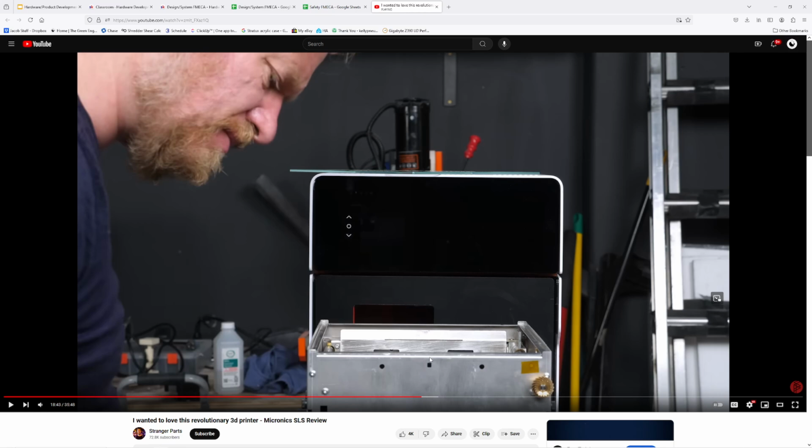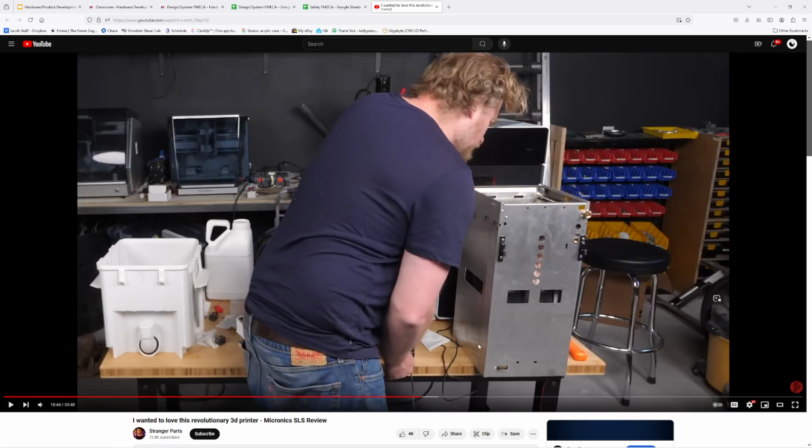So he's talking here, basically, he thinks that this auger is tilted or something, and so it's rubbing against the inside of the tube, and that's why it's jamming up. Or there's so much force on it from the compacted powder that it's putting too much torque on the thrust bearings on the inside, or pinching something, right? I've had some designs like that in the past where I haven't had adequate support when lifting. For example, I built this bike rack for a motorcycle, and when the machine was halfway down, it was fine, but when it went all the way down, it was tilting in such a way that it was pinching on the bottom, and it required massive amounts of torque to overcome that to start to bring it back up. And then once it got halfway up, it was fine. It would start to not be torqued as much, and would come into better alignment and not pinch on the nut that was on this Acme all thread.